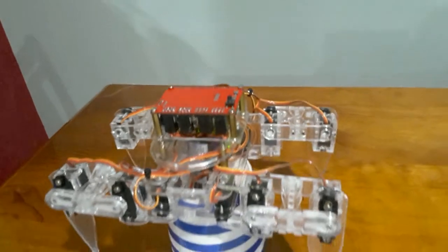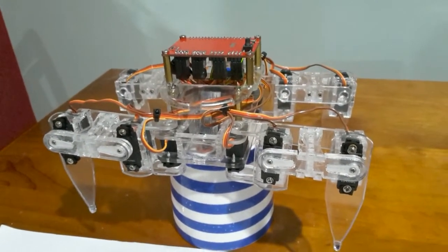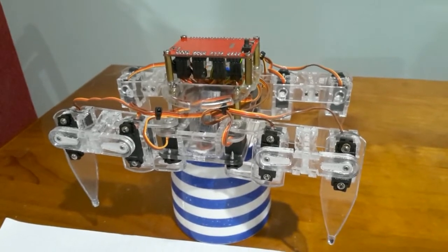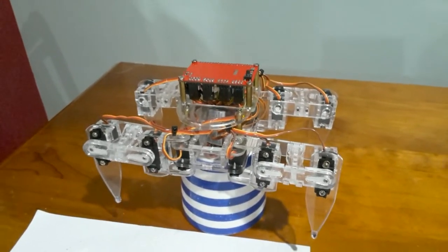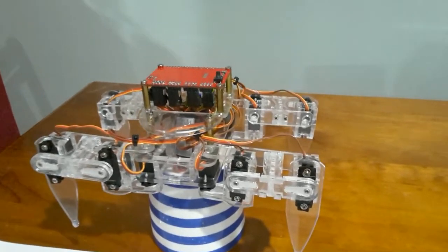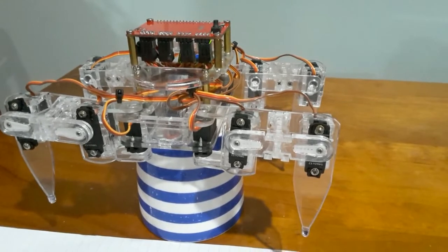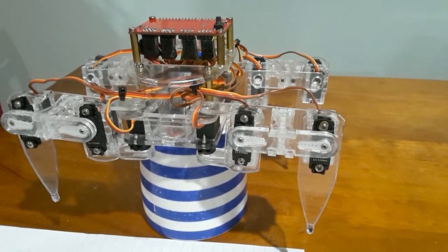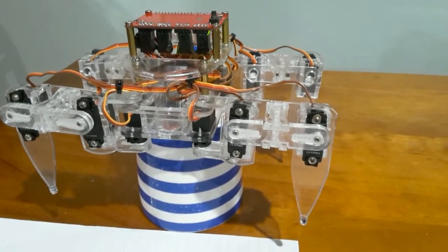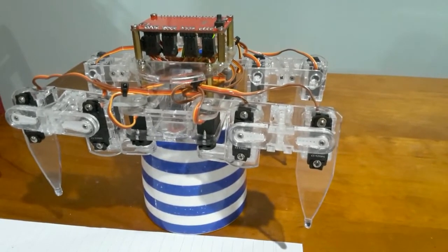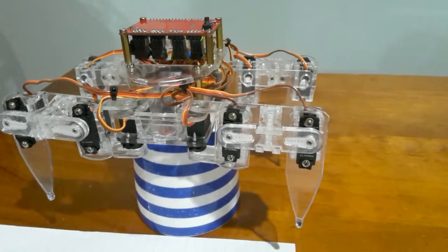Now, just a few little basics here. The PCB that controls all the servos on this robot is an ESP32, and I control it wirelessly from my computer, and all my software is programmed in MicroPython. When I wrote my drivers for controlling the servos, instead of setting the servos in degrees, it sets them in radians. And I did this for a reason, because all trig functions in Python return radians, not degrees.